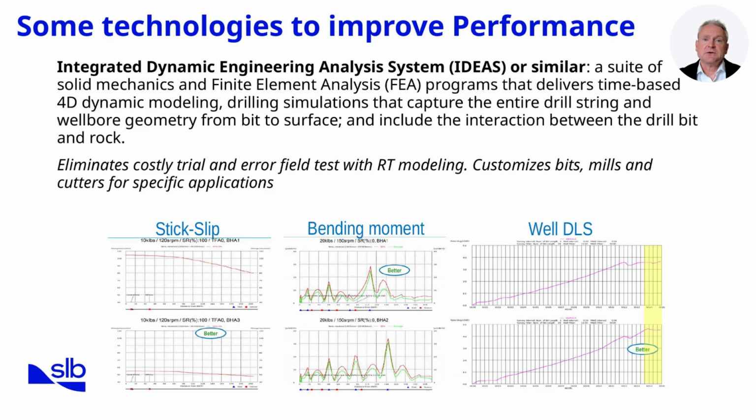Here we focus on the Integrated Dynamic Engineering Analysis System, or IDEAS, which is an advanced modeling suite. Unlike static planning tools, IDEAS delivers time-based four-dimensional simulations that represent the full drill string and wellbore geometry from the bit to the surface. This system applies solid mechanics and finite element analysis to capture dynamic interactions between the bit, the string, and the rock. It allows us to evaluate bending moments, stick-slip behavior, and the impact of dogleg severity on the drill string. By modeling these effects in real time, IDEAS reduces the need for costly trial and error field testing.